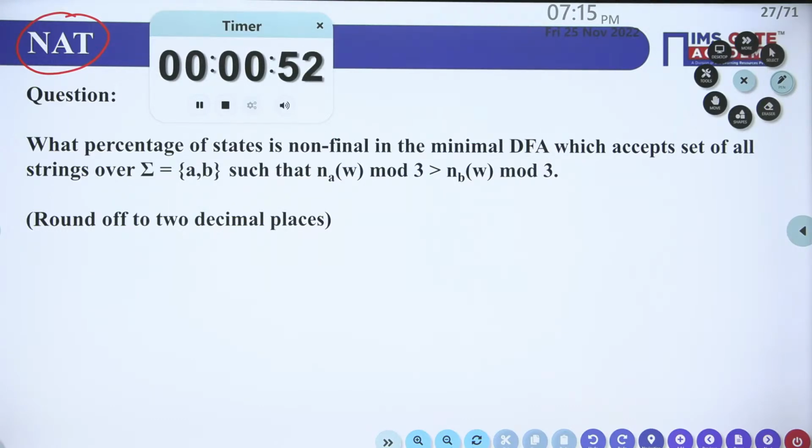Krishna, why is it less than or equal to? Why is it not just less than? Okay, Ramakrishna, that's a good question. This DF is known as the depth of the flange. When the depth of the neutral axis is less than the depth of the flange, it means the neutral axis lies inside the flange.